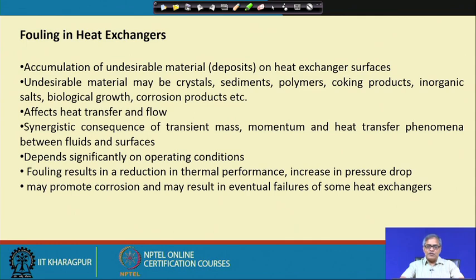So, from the heat transfer point of view, I will not find any difficulty, but due to the change of the dissolved solid, the deposition on the wall will change, and obviously that will have some effect on the performance and ultimately maybe on the serviceability, on the life of the heat exchanger.